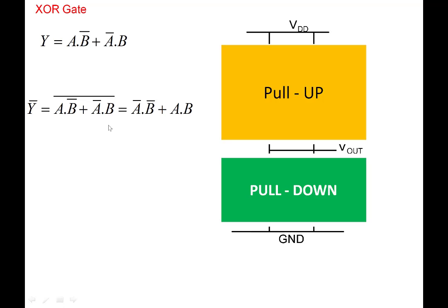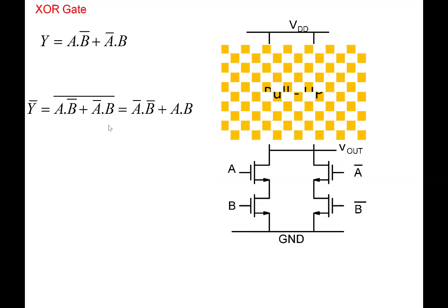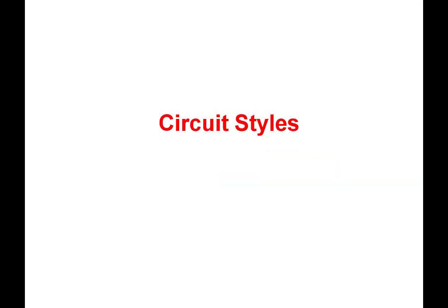All right. This we had seen earlier, how to construct a NOR gate here. So let's skip that. Now, is this the only way in which we can implement logic, for example, NAND gate and NOR gate? It turns out that we had seen earlier NMOS logic with resistive load. So there are several other logic families available. You can call them logic families, or you can call them different styles of implementing a circuit.